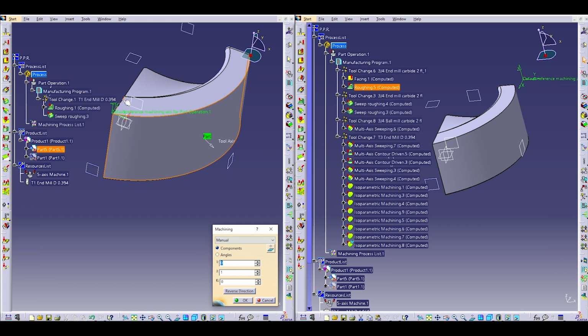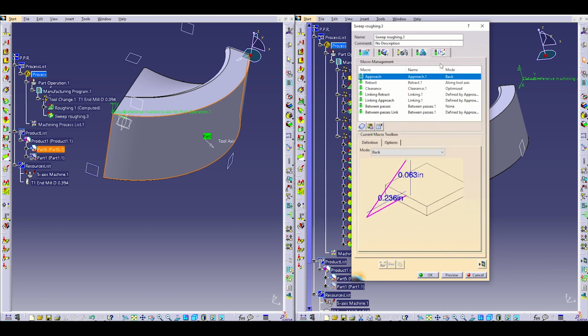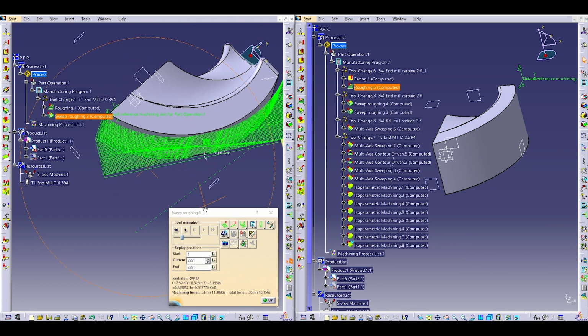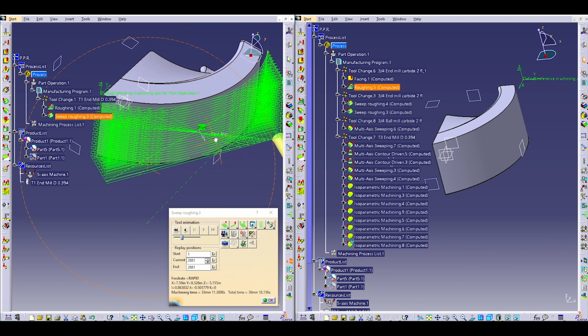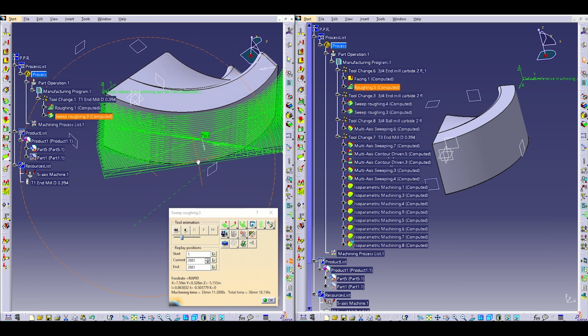And the machining axis is going to tell you which way you're going to point it in the way that it's going to machine. So you set up your macros and micros. You can see what we have. If we hadn't roughed, that would have crashed right into the stock, that original roughing.